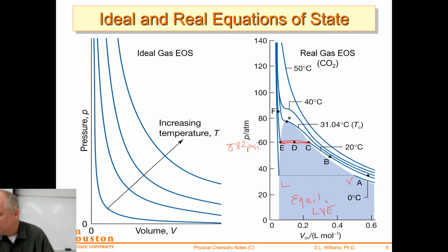It's a big truck. So, okay, what is the vapor pressure at 0 degrees C? It's way down here, so it's like 35. So what's 35 times 14.7? 515. So even at 0 C, liquid CO2 would have a vapor pressure of 515 psi. Okay, so yeah, it's kind of high.